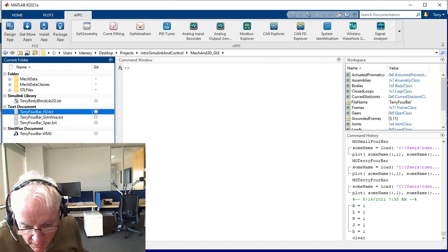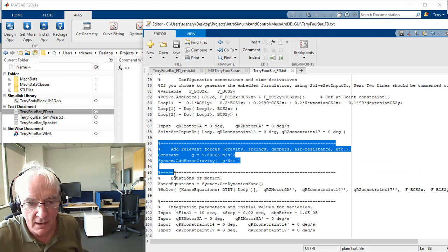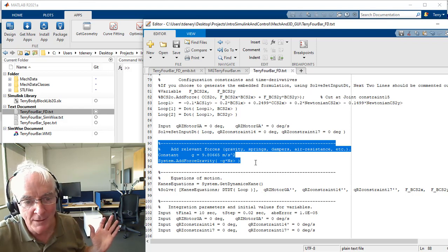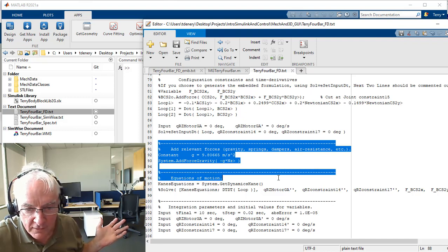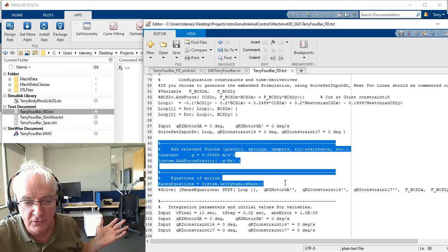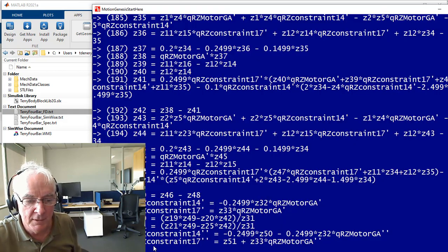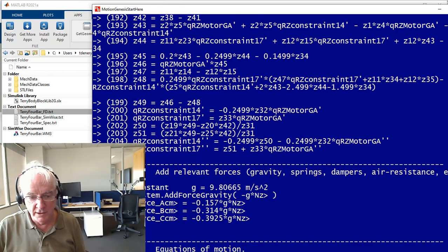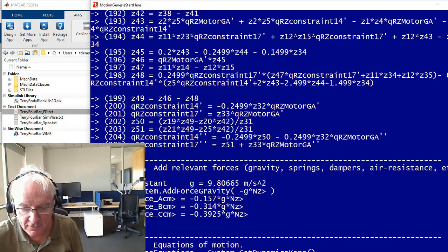And so now we go in and apply the forces. The only forces really, well, torques are well, they might be in that formulation. I'm not sure. Actually, we'll find out. So they certainly get there by the end, right? And so what I'm going to do is add the forces of gravity, and then let's solve for the equations of the overall system, right? And again, what I'm telling you is that the approach we're taking this time is to reduce the system to 1 degree of freedom, right? And here's where we do the system dynamics, and I hit enter.